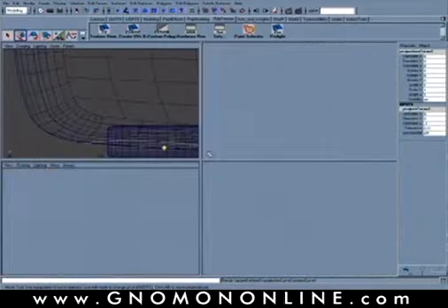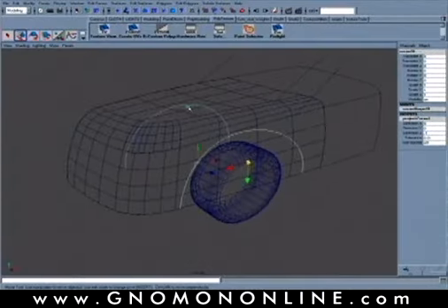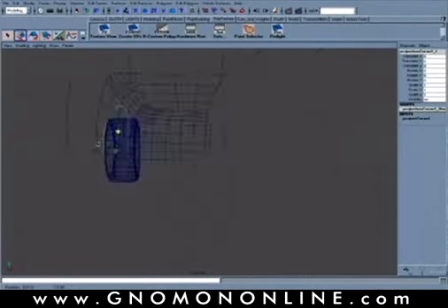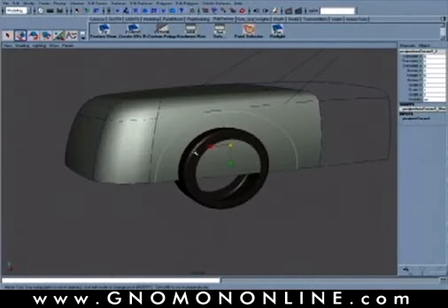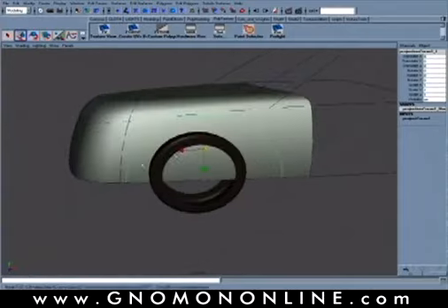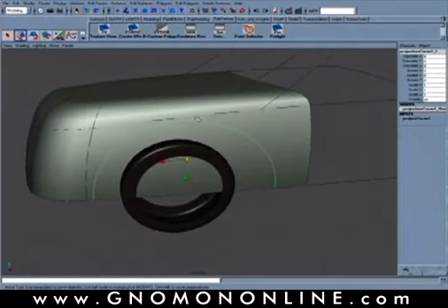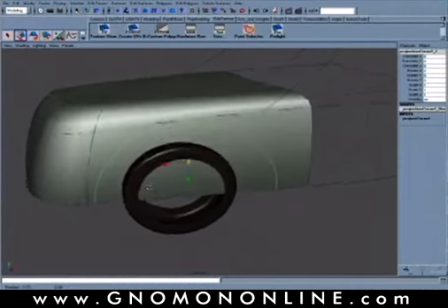Okay, this will create our curve on surface this time. So we'll have really two curves, one that was off the surface and then the actual curve on surface that was projected on to the model there. Okay, at this point we're going to trim this one. This is going to be our main hole going into the body, so we want to make sure that we don't see a surface coming through the middle of the tire.